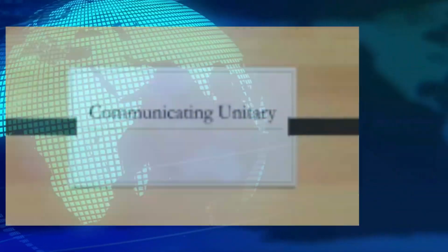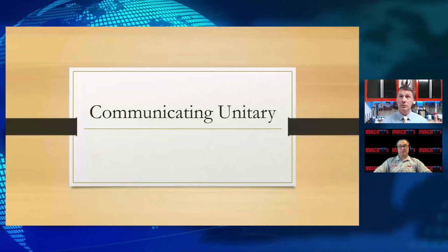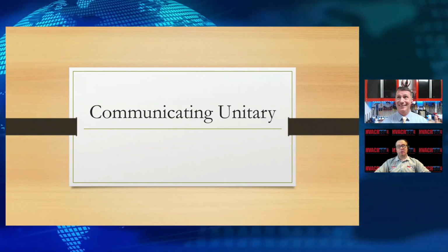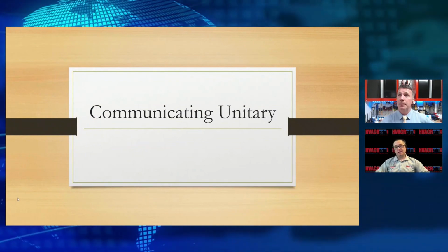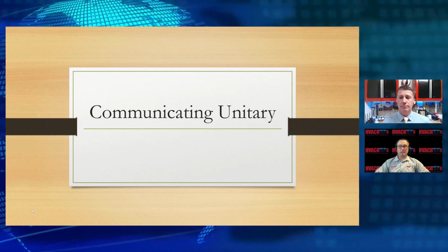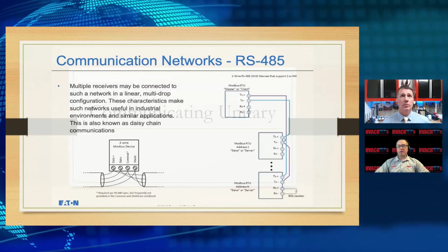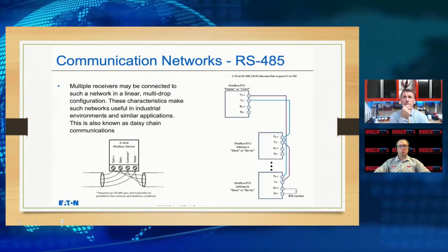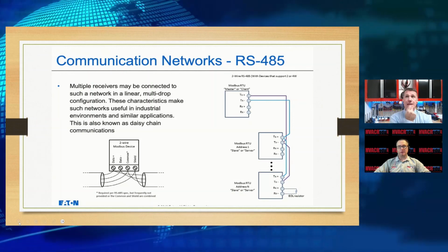So, Todd, you spent a lot of time on the BAS side of things, building automation, and you guys have a great course over at HVACR EDU. A couple of these slides are in reference to intro BAS stuff, because BAS and our unitary communicating really are very similar. Six of one, half a dozen of the other, right? They're very similar in the way they communicate. It's going to be a DC voltage, usually 5-volt DC, and very similar to pulse width modulation. We may have heard that in the industry, right?